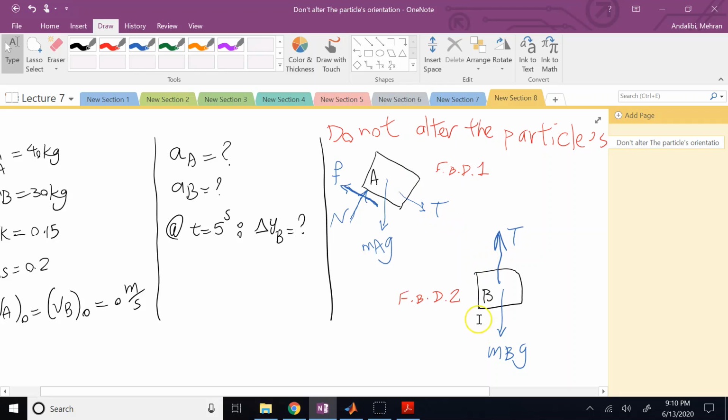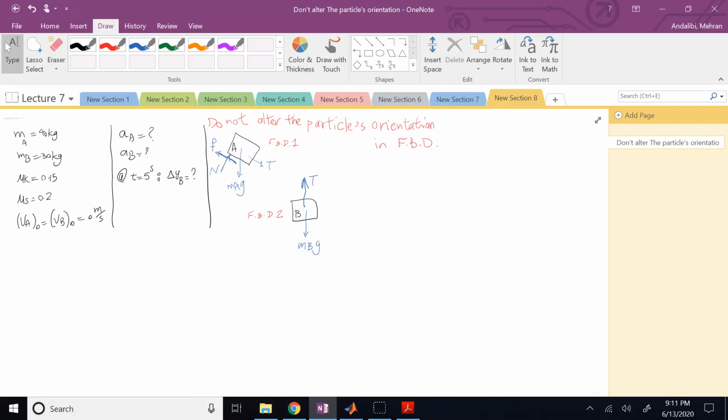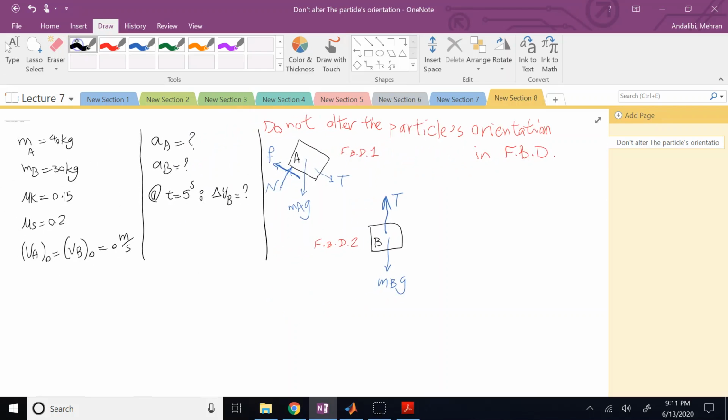First, let's find out why the system moves down. Let's talk about that. How do I know? So this is how you can find out. If you combine these two objects together, that's another way to draw a free body diagram. And actually, in this case, it is preferred over individual ones. So one way that you can act when solving dynamics problems for a system of objects is to combine the system into one single object and draw the FBD for that. So let me call this FBD3, if you don't mind.